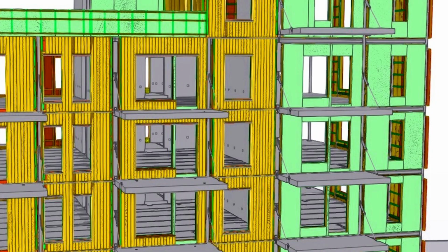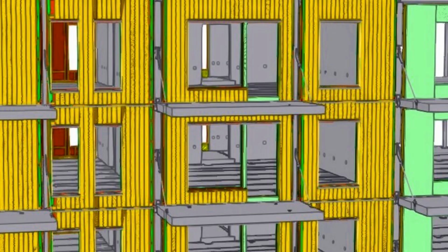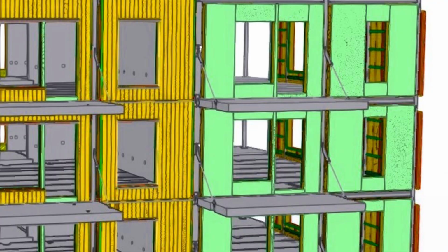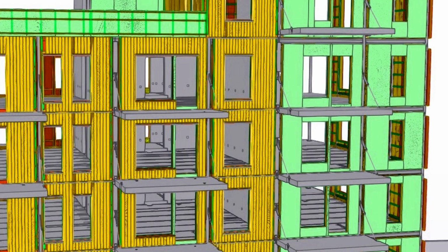In the building model in the drawing, the left side shows the vertical timber boards that are installed on the element in the factory. In the part of the building on the right, the element is covered with wind barrier plasterboard in the factory, in front of which a brick facade is laid on the construction site.